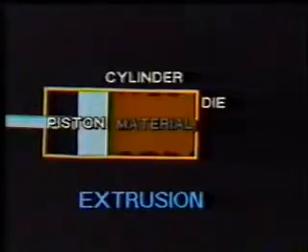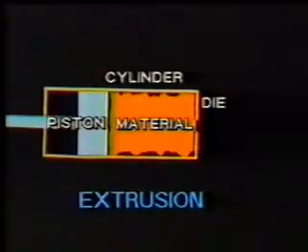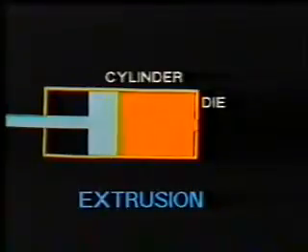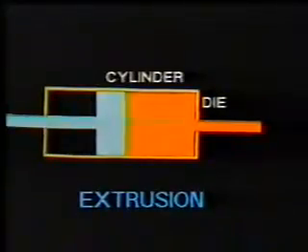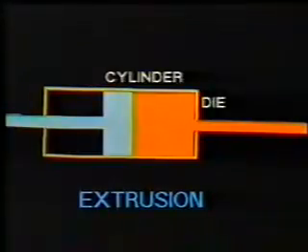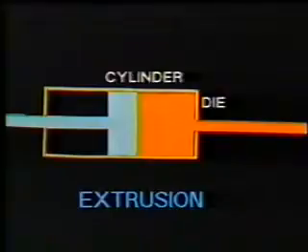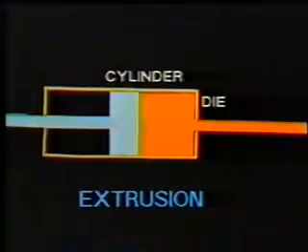Let us now see the process by which the material is extruded. The material in its plastic state is kept in the cylinder. It is then pushed by means of a piston against a die. With the pressure force, the material is first upset to fill out the container and then emerges out through the die. The process is continued till a small sized stub of material is left, while most of the material has taken the extruded form.